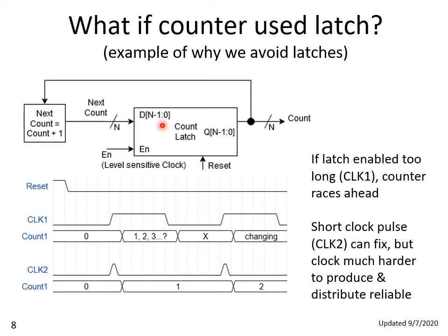Suppose this was reset to 0 and it was initially not enabled, and that's like this waveform here, or really either of the set of waveforms below here, but let's concentrate on this one first. So if the enable is low to start with and we've asserted a reset, forced the value to 0, okay, great, no problem so far. We reset the latch, nothing bad happens.